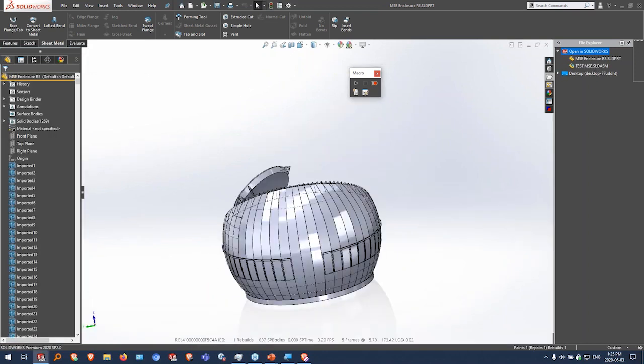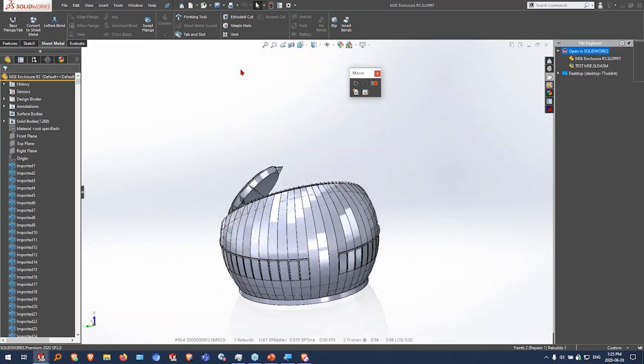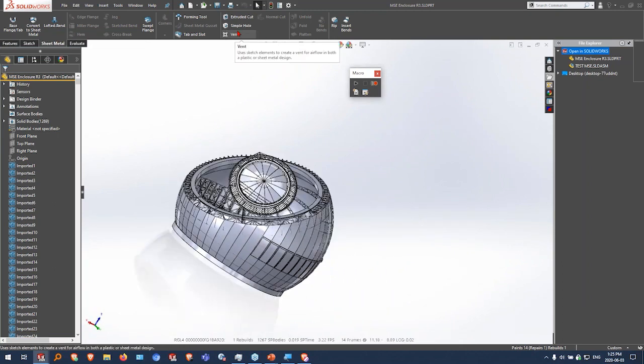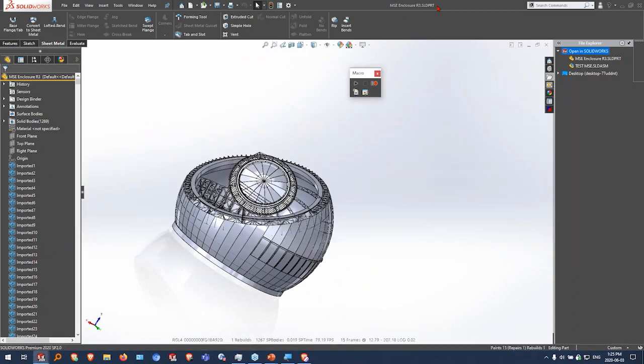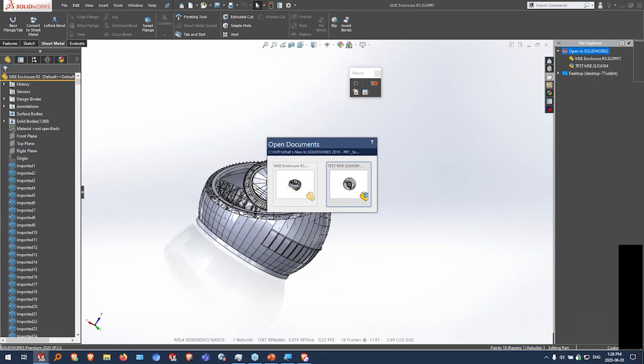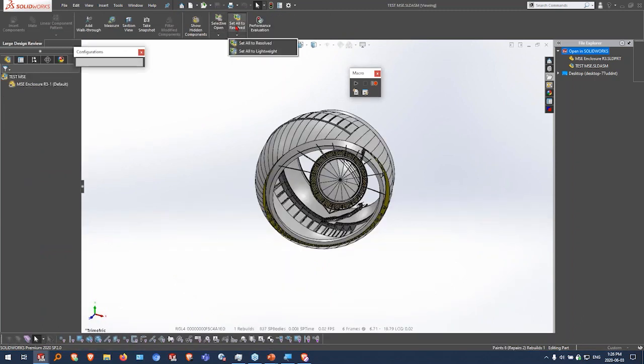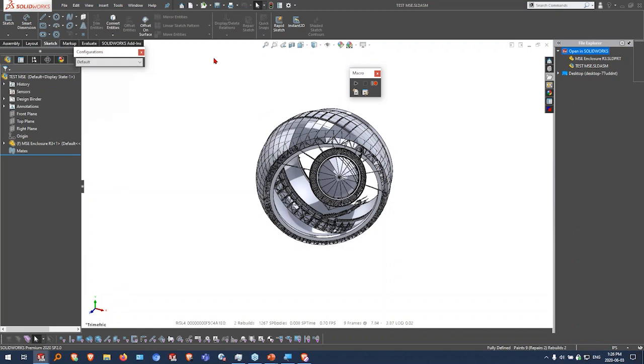So that open process indicator I mentioned before, I highly recommend everyone keeps mindful of what that indicator is doing as it's doing its load, just to see, is it hanging on a specific component? For example, there's a massive assembly that this file is associated with. It would hang on here for a while. And if you try loading that part file first, if it is hanging on one, then switch over to the assembly file. It might load significantly faster for you. And let's switch back over here to my assembly here. And now let's set all resolved, because this will now resolve here fairly quickly.